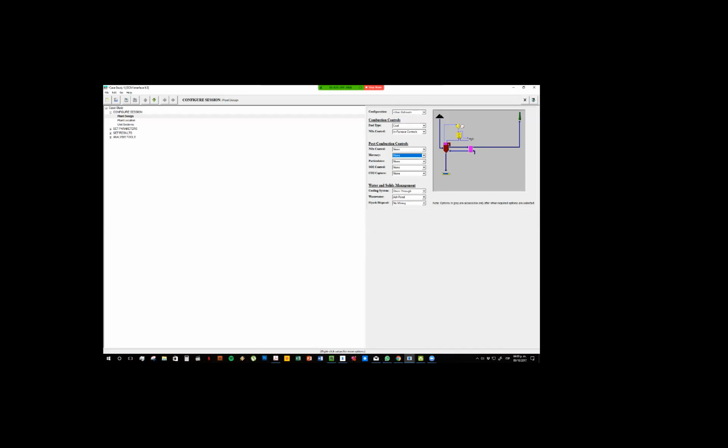Particulates, which are suspended particles of small size, very bad for the lungs, for example, you can control with two different things: a cold-side ESP, an electrostatic precipitator, or the fabric filter, right? And we need to have a control for the sulfur oxide and carbon dioxide. So we have wet FGD or lime spray dryer, but that is only an option.